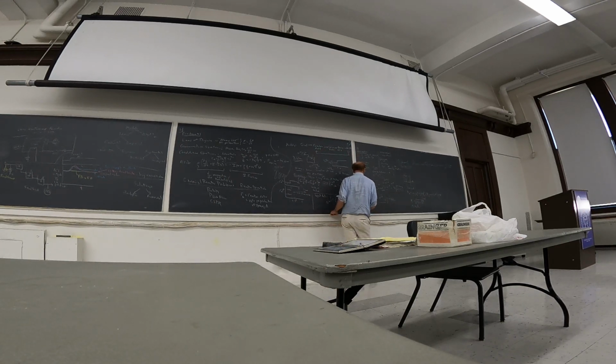If I divide through by V, and I let tau equal big V over little v, and if I assume v out is v in, then I can rewrite this equation as dCA/dt is equal to (CA in minus CA) over tau.